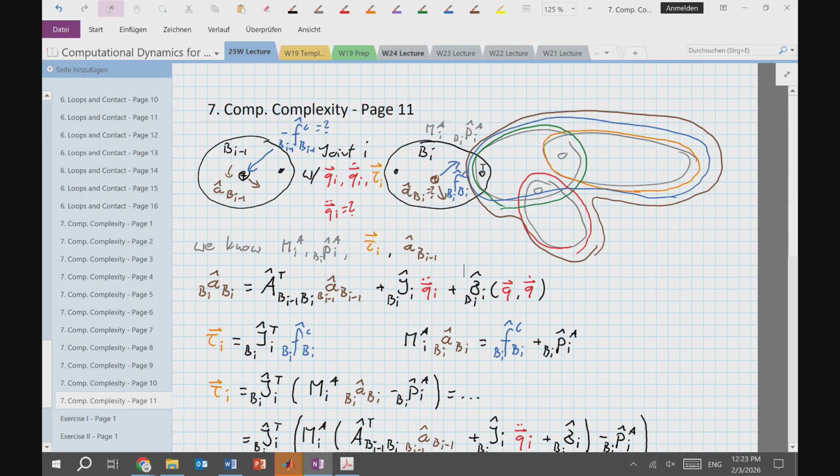Right? And then you see where this is going, because if I know the articulated inertia of BI plus 1, I can do one last combination where I combine this with this to get the complete articulated inertia now of body BI. And so I start from the leaf. For each body that I visit, I first compute its independent articulated inertia and then combine that articulated inertia with the articulated inertia of its children. And I can do this in a recursive fashion moving inwards.